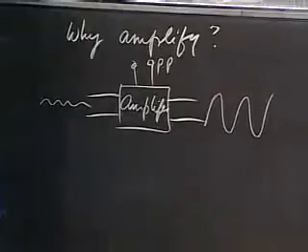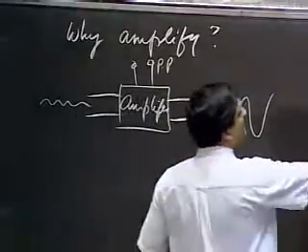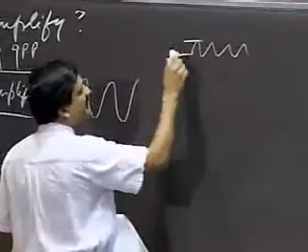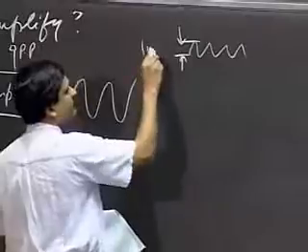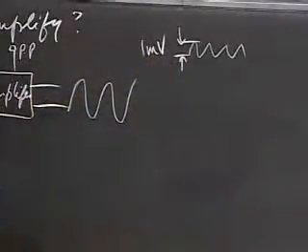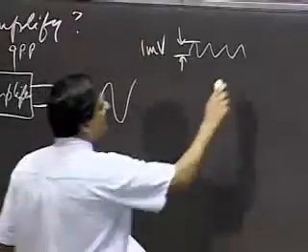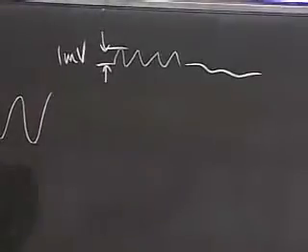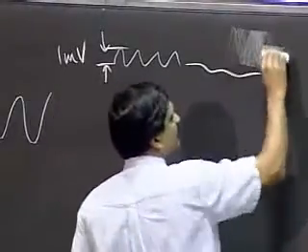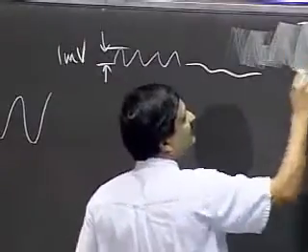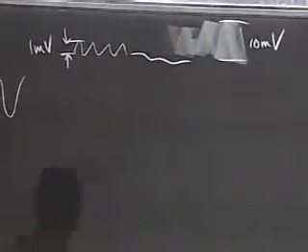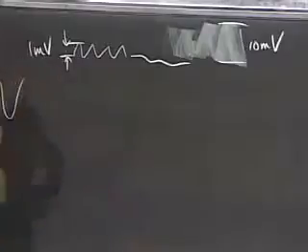So that's an abstract definition of an amplifier. And let's take a look at an example of why we may need this. Let's say I have a small, useful signal, and let's say the signal has a 1 millivolt peak-to-peak, and I'm looking to transmit the signal over a wire to some other point. But let's say that in this environment, it's a noisy environment, and in this environment, let's assume that some noise may get superimposed, and if I